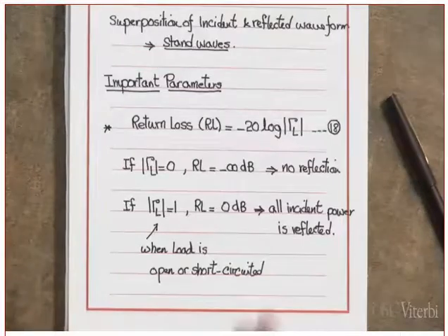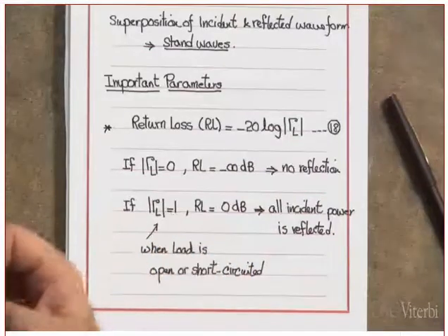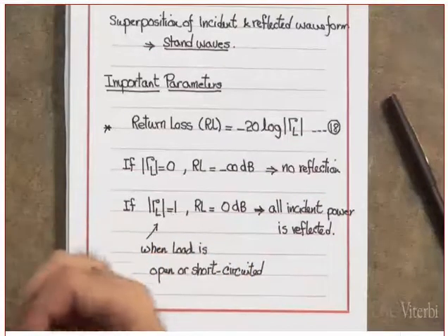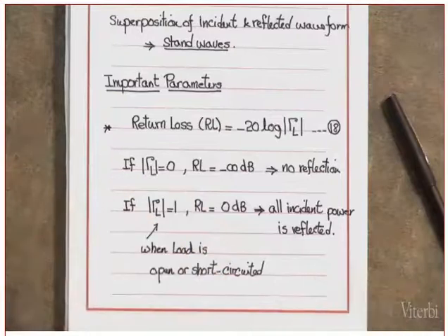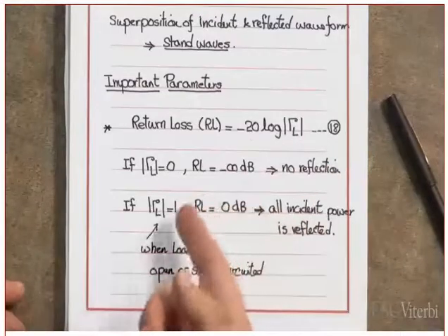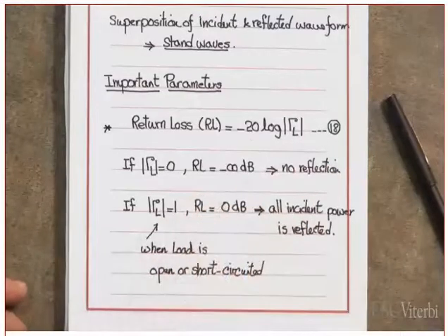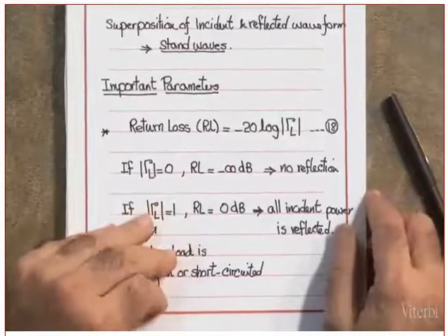You can use the transmission line if you don't have a given inductor or a given capacitor. In other words, if you need a value for a capacitor or an inductor, but you don't have that value, you can replace it by a transmission line that is either short circuit loading or open circuit loading. Clear? We'll get to those in just a second.